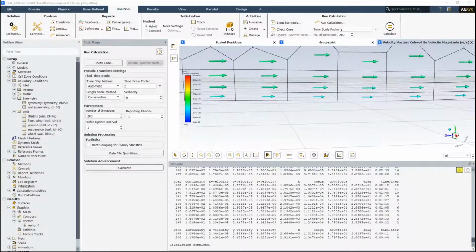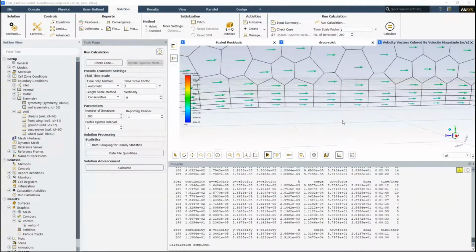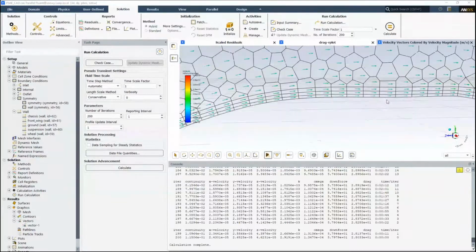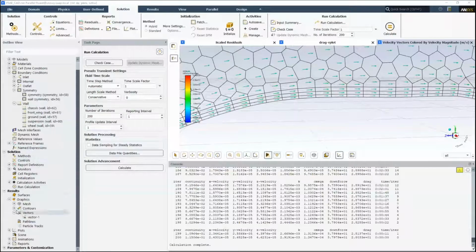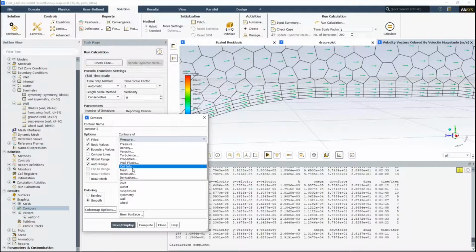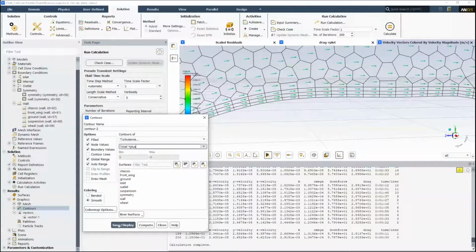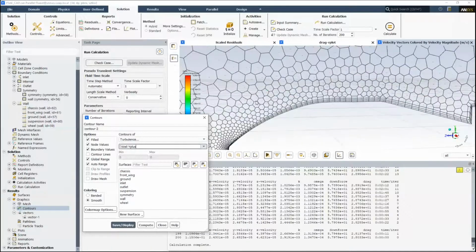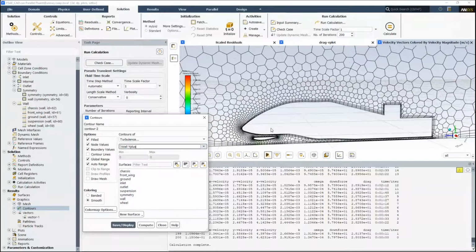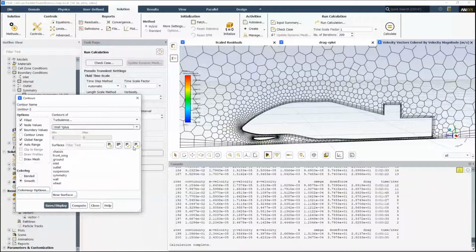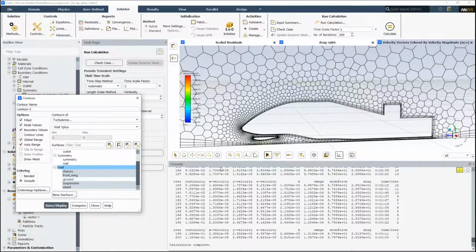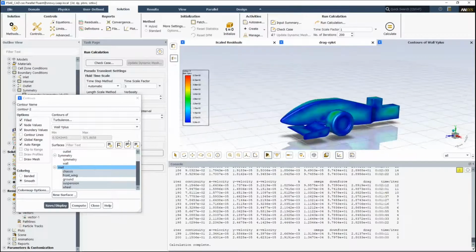So in this case, yeah, we definitely need a much better inflation mesh to pick up what's going on properly. One thing I will show as well that we can do in here is look at our Y plus value. I'm expecting a minimum Y plus of about 100 here. It'll come up on the legend, but let's plot the Y plus value on all the walls except the ground. We're actually getting a minimum value of around 0.5.